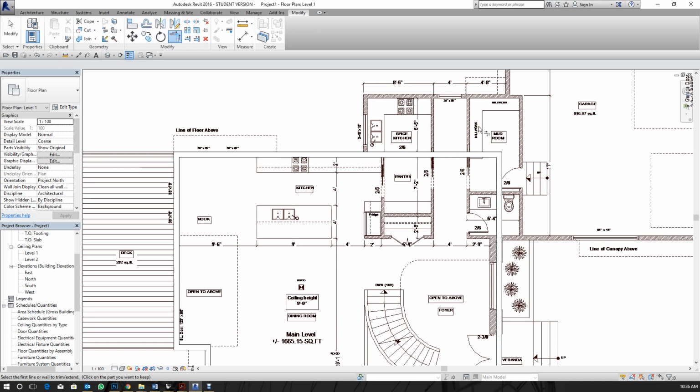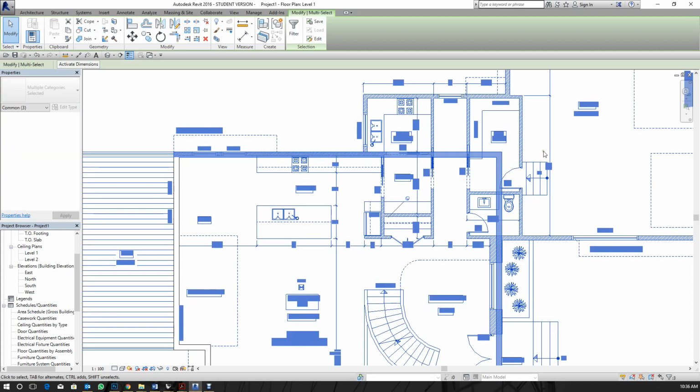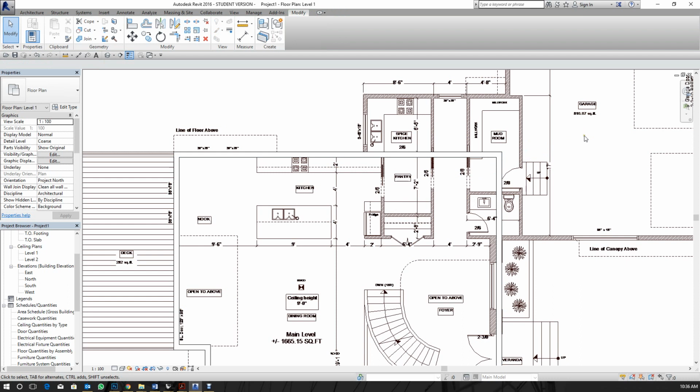So trim in Revit actually works differently from your conventional trim in AutoCAD and Rhino, where you select the components and then you trim the side you want to trim. In Revit it works more like a chamfer, where you select one line and you select the other line and it just closes it.